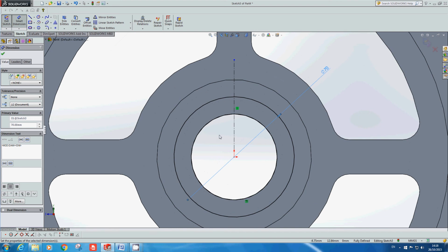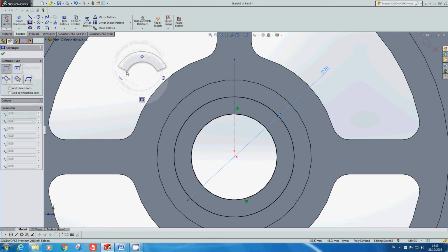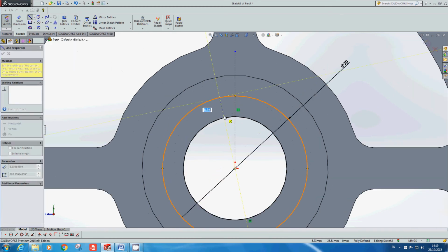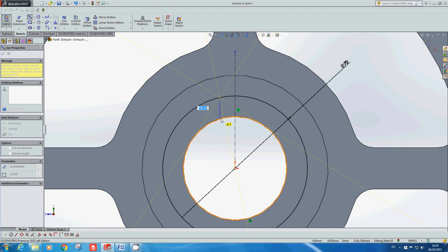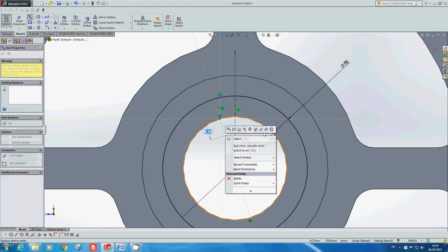And what do we need next? A line. So go across the line again. Just for that wheel, I'm right clicking and holding and just moving it slightly. So straight up is dimension, left is line, right is circle, and that's rectangle again. I don't want rectangle, I want line. So that's just a quicker way of doing it. You don't have to use it. So that's my line there.